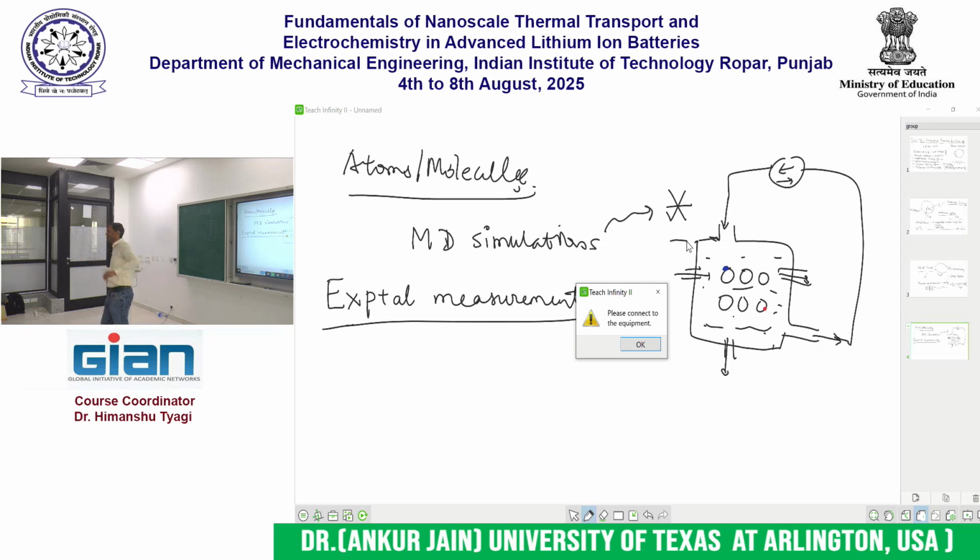Maybe. I ask a similar thing. When we think about the small module, then this thing comes. But when we think about a whole battery pack, if we increase the 1 mm gap, it adds up. It will create a huge difference in the whole total battery capacity. Sure, because one line can be removed. Sure. So you have to come up with what is the optimal spacing there. Maybe not 2 mm, but maybe 1.5 mm will give you a reasonable compromise between the two. I don't know the answer to it.